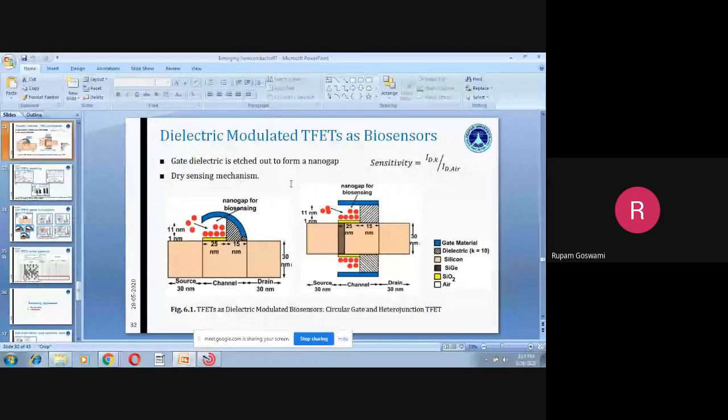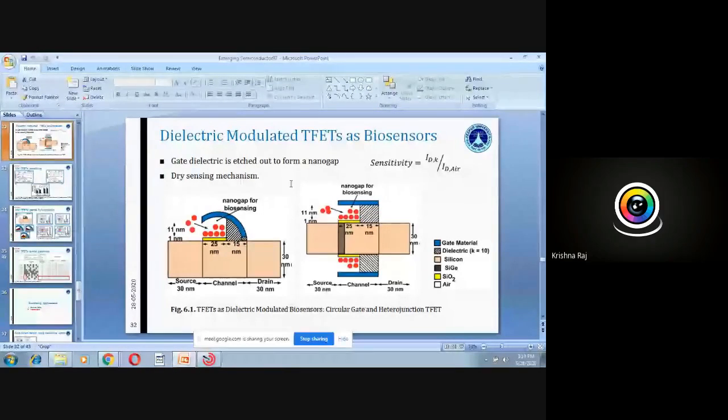In future, if you are trying to work on FinFETs, you can look out for tunnel FinFETs, which means you make a FinFET out of a tunnel FET, or you apply the same fin shape structure to a ferroelectric field effect transistor. I believe you will find some very exciting results. People are starting to work on such devices, combining the advantages of FinFETs and TFETs. I hope I'm able to get across to you on this point.